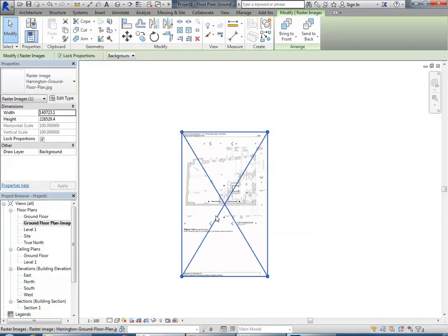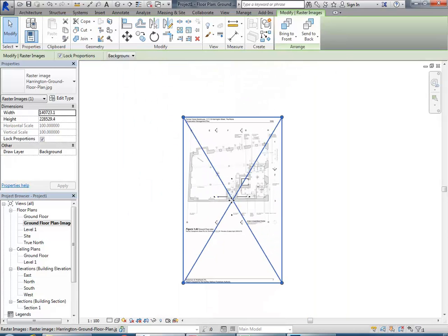So one of the first thought processes you should have working with Revit is the way you want your drawings to appear in the end. It's something you can change later on. You can rotate the whole project, but it's difficult because in Revit it physically rotates the objects when you do that. What you can change very easily is true north. So don't worry so much about the actual north direction. What we're thinking about here is project north. So in other words, the orientation of your drawings relative to your sheet.